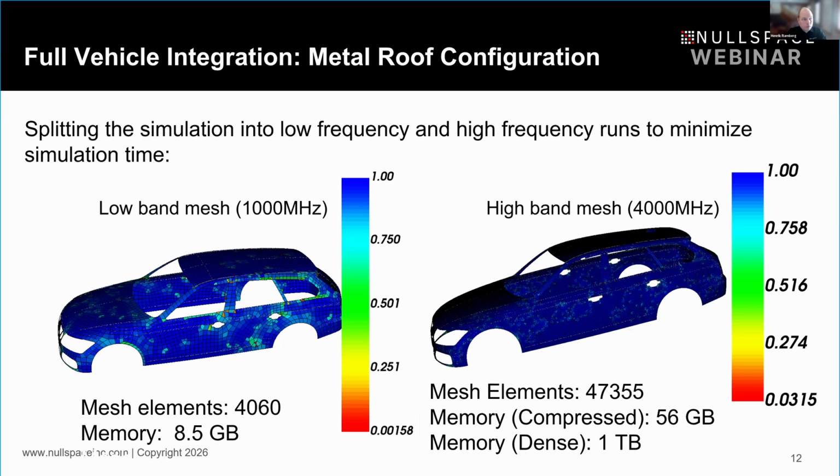No, exactly. Here, you divide the problem into two different parts because when you go to the high frequency part here for the 4 gigahertz mesh, we are going to have a significantly larger amount of mesh elements, which is going to take longer to simulate.